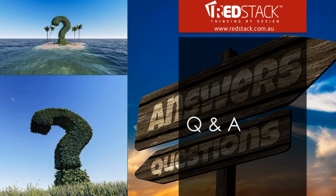With the server, there's obvious requirements. So it's probably preferred on a workstation, because on a workstation you can get much better graphics card requirements. But it's a dedicated machine purely for processing those tasks. I mean, theoretically, you could nominate a client machine as the task server, but then while those tasks are running, if that user is now using Revit, there's going to be a challenge there.